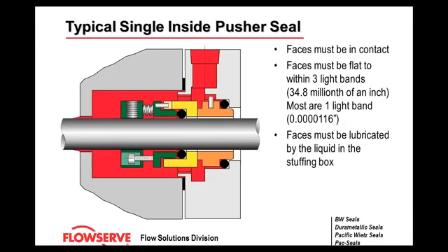Now, to talk a little bit about flatness and exactly what flatness means. If you could picture yourself standing on a big concrete floor, and next to you you have, let's say, a laser level. And off in the distance, someone's out there with a measuring device, some sort of yardstick, going around taking measurements, reading off of the laser level.